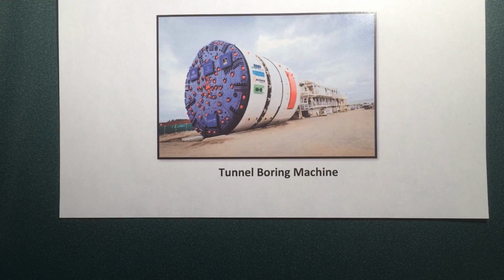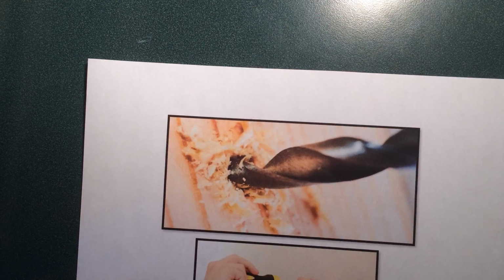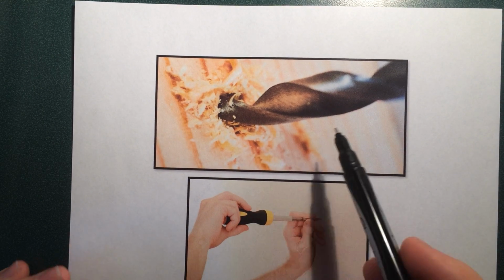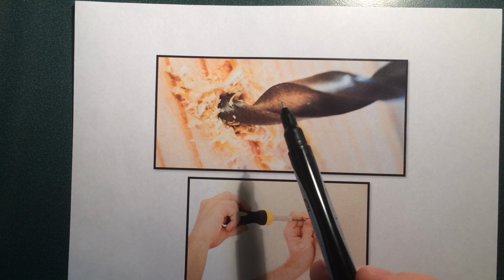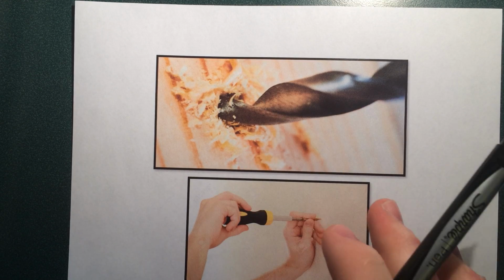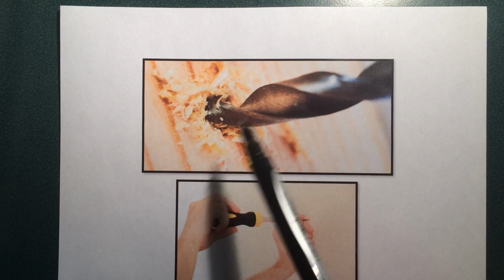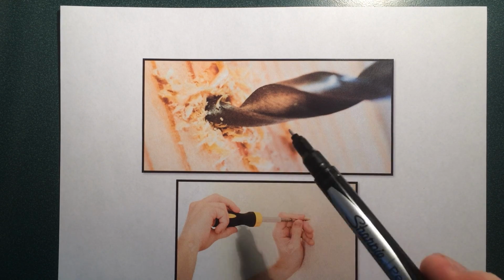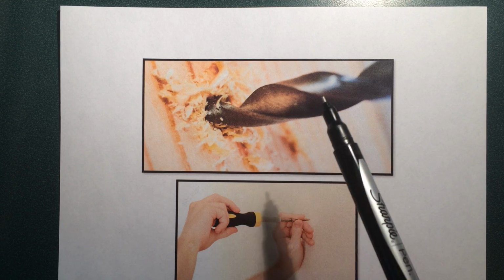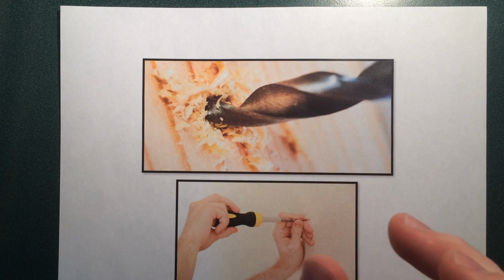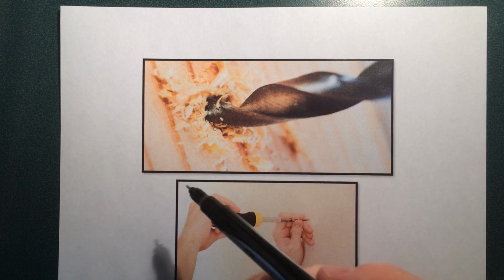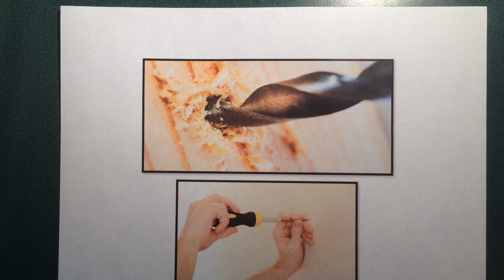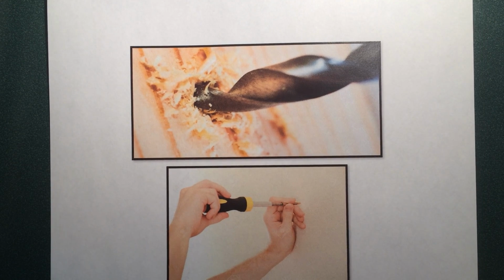Alright, and I've got a few more practical examples that you probably use, maybe once or twice a week or in a month. Got a drill bit here, drilling into wood. So we can figure out optimum efficiencies and that type of thing of a drill bit. Because it turns out in torsion, when you're twisting something, most of the torsion is picked up by the outside of the drill bit. So you can basically hollow out the inside and have that drill bit do the same job. So we're going to do some calculations that look at that, and then of course the hollow drill bit is a lot more efficient, uses less material.